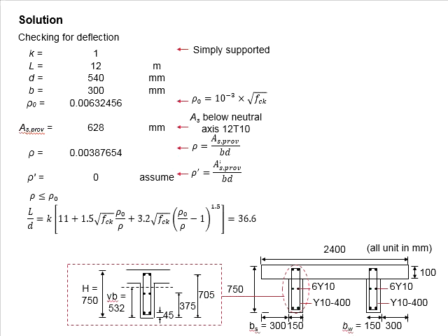The prestressing force itself is adequate to resist the ultimate limit state load. You also know that for the serviceability limit state, the member is designed with partial prestressing. Therefore, you should theoretically provide the longitudinal reinforcement bar to control the cracking.